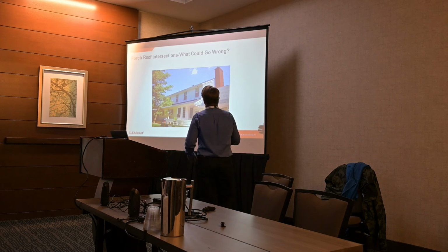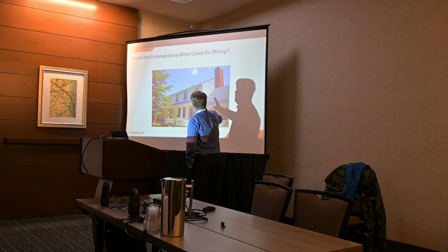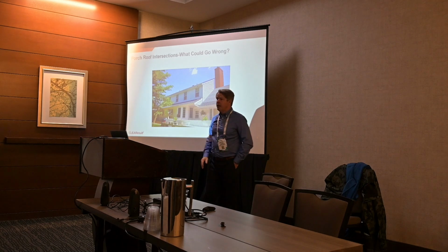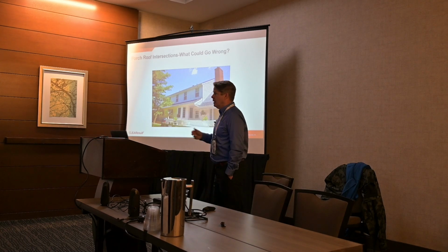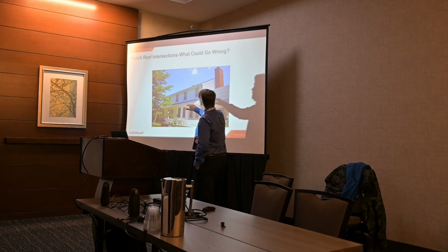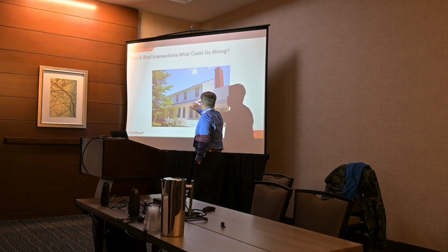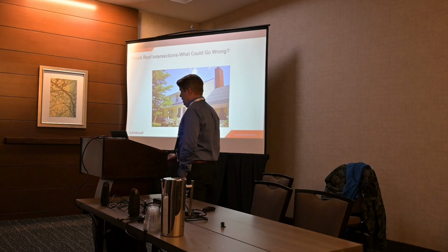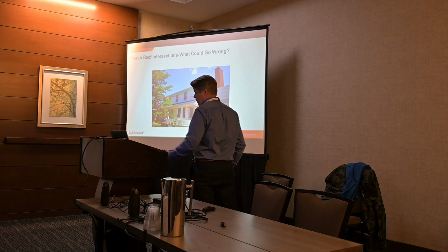Okay, so this is a porch roof intersection like I was talking about before. And if this is a problem or not really depends on how this house was framed. If they framed the house and then they framed the porch and attached it to it, then the exterior walls will be sheathed, and there'll be a transition blocker here. But if they framed it all at once, the bottom of that wall won't be sheathed, and most likely the floor joists will be cantilevered and unsealed, which means that when ventilation air flows up into this porch, it's going to go between the floors, just like a knee wall, okay? Access obviously is a problem there. So just details like that are the sorts of things that we need to look at or think about anyway.